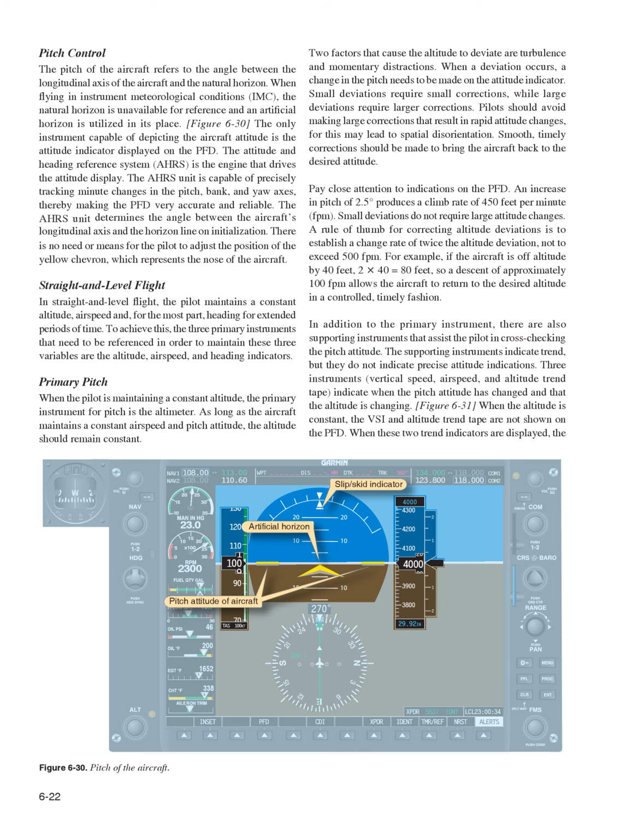Pitch control. The pitch of the aircraft refers to the angle between the longitudinal axis of the aircraft and the natural horizon. When flying in instrument meteorological conditions, IMC, the natural horizon is unavailable for reference and an artificial horizon is utilized in its place. Figure 6-30, the only instrument capable of depicting the aircraft attitude is the attitude indicator displayed on the PFD.